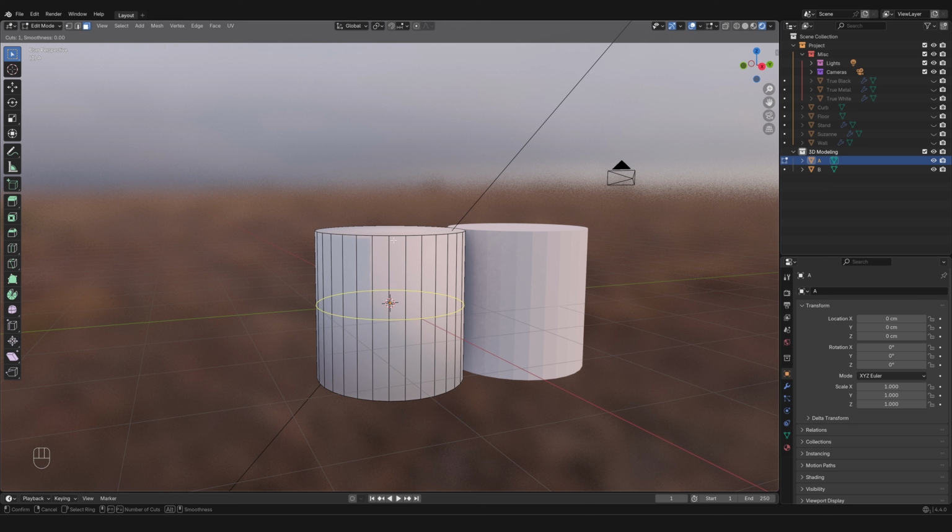And if I move over here, I can see that I could also introduce edge loops vertically to these faces or maybe make a cross section. Now, if I were to click with a right click, I would sort of cancel the operation at this stage. Whereas if I click with the left, I am moving on to the next stage.